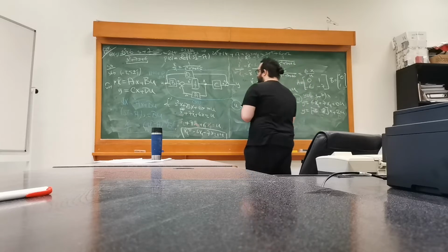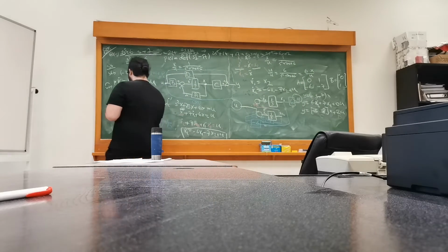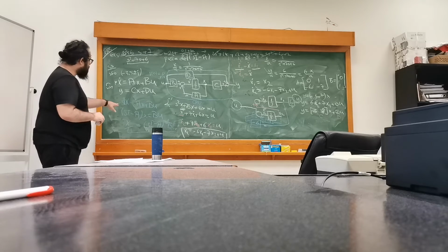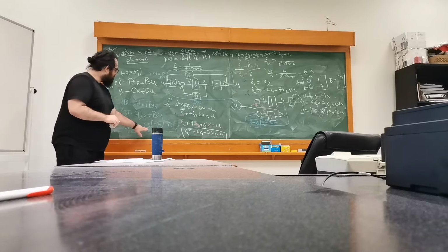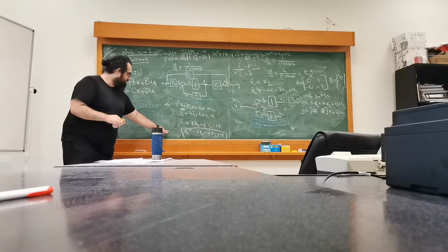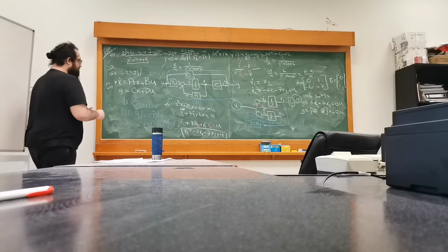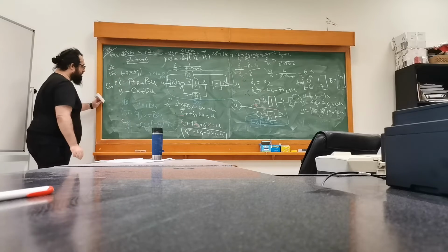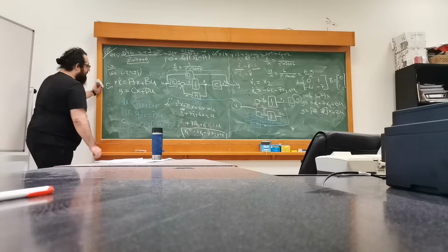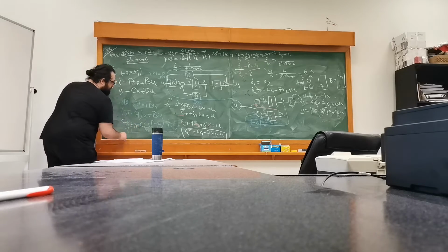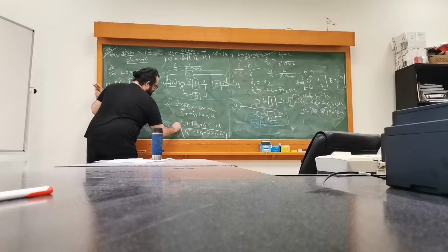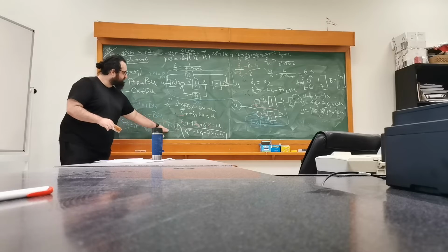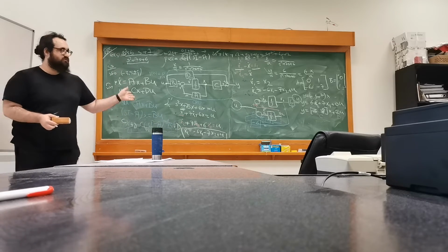So it's quite easy because we will again use this portion here. It's already prepared. We have the x-u relation, (sI minus A) inverse times B. The only thing left is to pre-multiply it with C, because then we will get Cx divided by u. And if I add D, I'll get basically the transfer function. So C times (sI minus A) inverse times B plus D should give us the same transfer function.